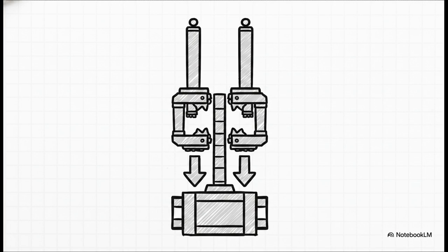Because the well is highly pressurized, it constantly wants to just spit the pipe back out, right? To overcome this, snubbing uses multi-cylinder hydraulic jacks that operate in massive 10-foot strokes, literally forcing the pipe down. It uses a tag team of traveling and stationary slips, which are essentially giant hydraulic jaws, to grab the pipe, push it down, hold it in place, and then reach up to grab the very next section. And all of this happens safely inside a complex blowout preventer stack to ensure the well doesn't erupt.